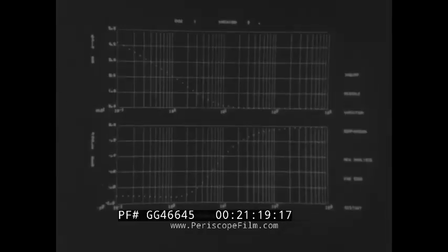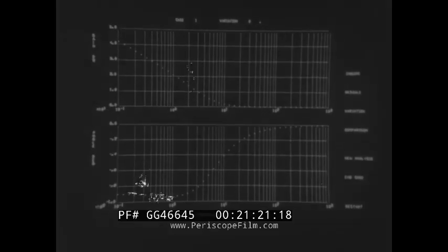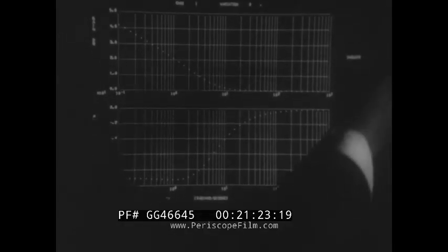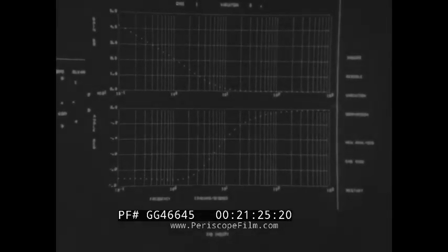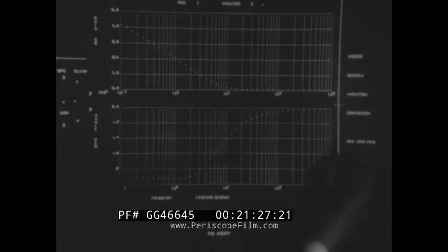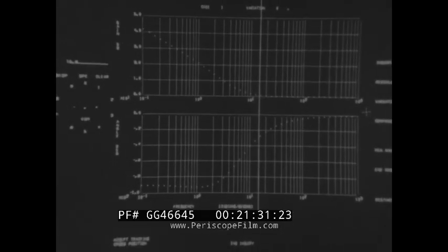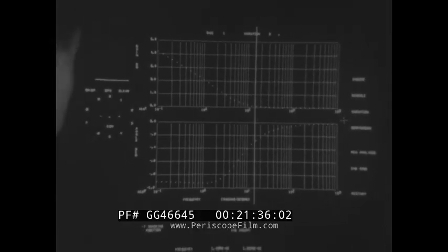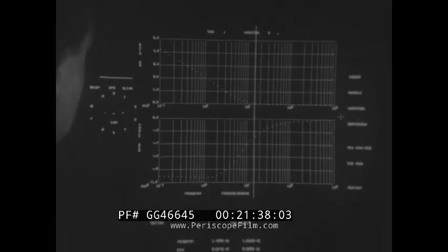The first technique, frequency response, produces two graphs which give the magnitude and phase angle of the response at specific values of frequency. After reading the data, the program computes the points on these curves and displays them. You will notice that the independent variable, frequency, is plotted logarithmically, while the phase angle and gain are linear. By moving the tracking cross to the position we desire, we can determine the exact values of gain and phase at that frequency. These values are displayed near the bottom of the screen.